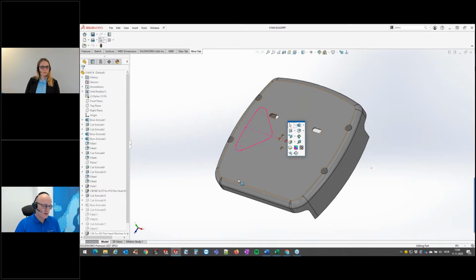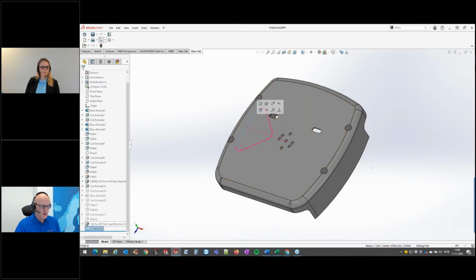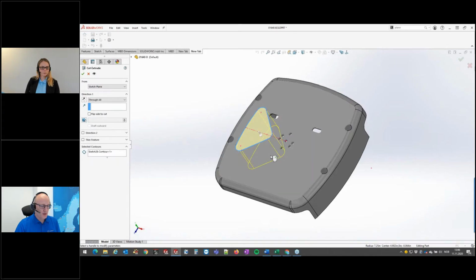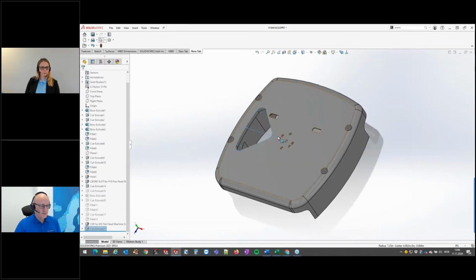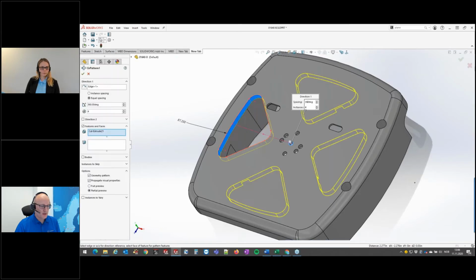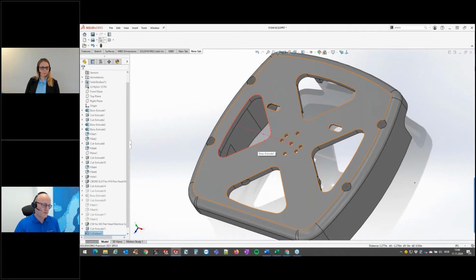So just going out from this, I can now make this cut. I'm basically just marking the sketch, choosing extruded cut, choosing through all, and then pressing the D key gives me this confirmation button here. And that's the cut. If I want to make a pattern of this, I can quite quickly apply the pattern this way. Pressing D key and OK. And as you can see, very little mouse movement is required to make this kind of operation.